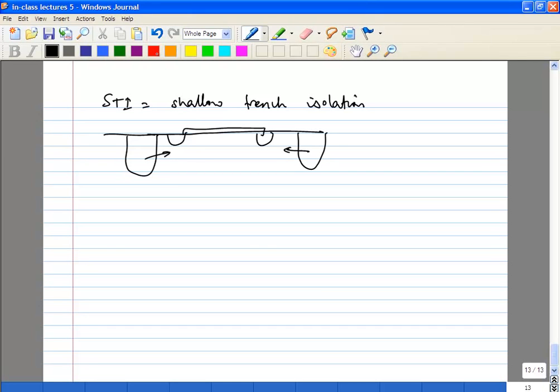What happens is, if your temperature changes, these trenches cause some amount of stress to the desired transistor, and the closer they are, the more stress they exert. That stress can change all kinds of parameters. It can change your VT, it can change mobility. At the end of the day, what you're interested in are transfer parameters like GM, and it will definitely change all of those. So you are designing for a particular GM, but in some of these deep submicron processes, it can be off by as much as 15-20%, which is a lot, obviously.